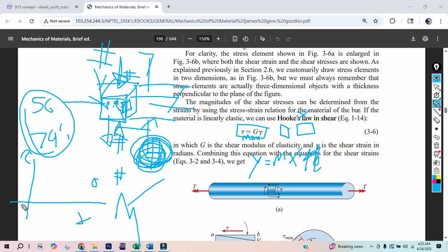And then if this is the tau, that's the y part, G is the slope, and then this is your angle. So if my angle is my independent variable, which they've been talking about, and it sucks because no one's going to measure the angle. The only way to actually measure anything in the material mechanics world is to put little strain gauges on, which are tiny little manufactured wires so small you can hardly see them.